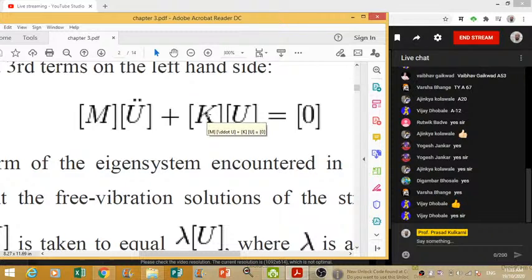But in modal analysis, nobody recommends that you apply external forces. So external forces are not there. You have to just type the frequency and the density of that component. One more thing: whenever you do modal analysis, transient analysis, harmonic analysis, or any kind of dynamic analysis, there must be a parameter called density.